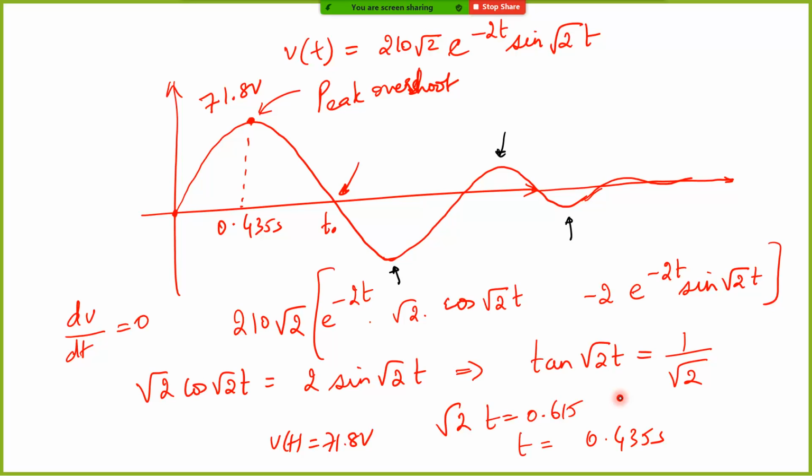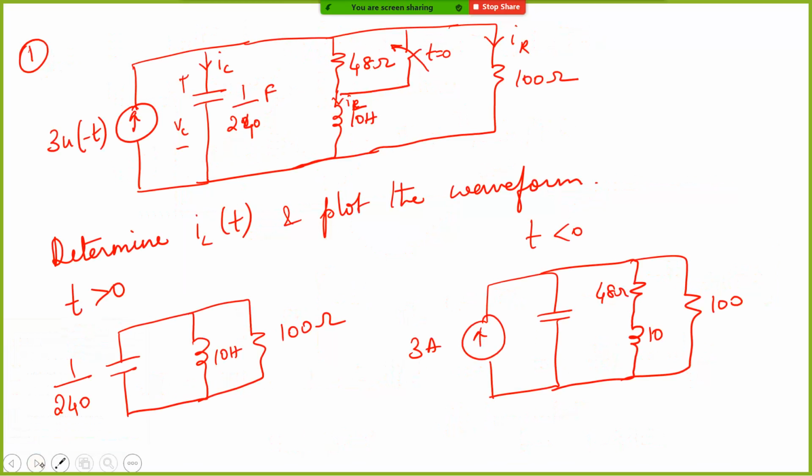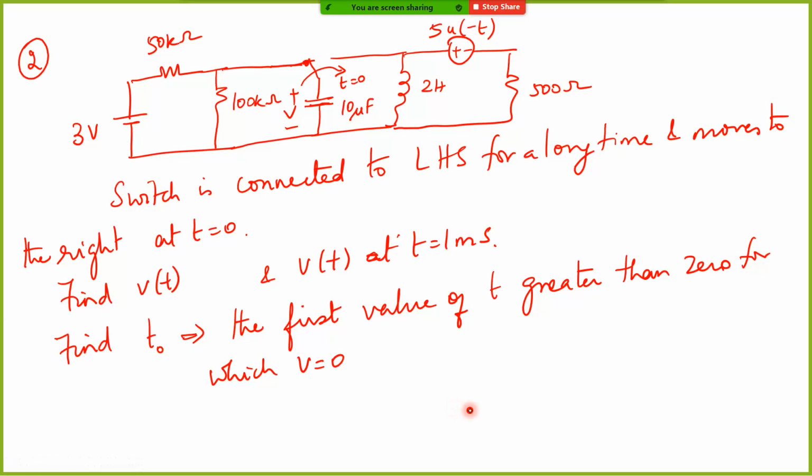In this case it becomes very simple, because there is only one sinusoid. But in the next question that I have given, you will most likely end up with B1 and B2 values, both of which are not 0. So it is the sum of the sinusoid and the cosinusoid. Sir, we can combine both of them, something like beta 1 sin omega t plus beta 2 cos omega t, into a single sinusoid with a phase.